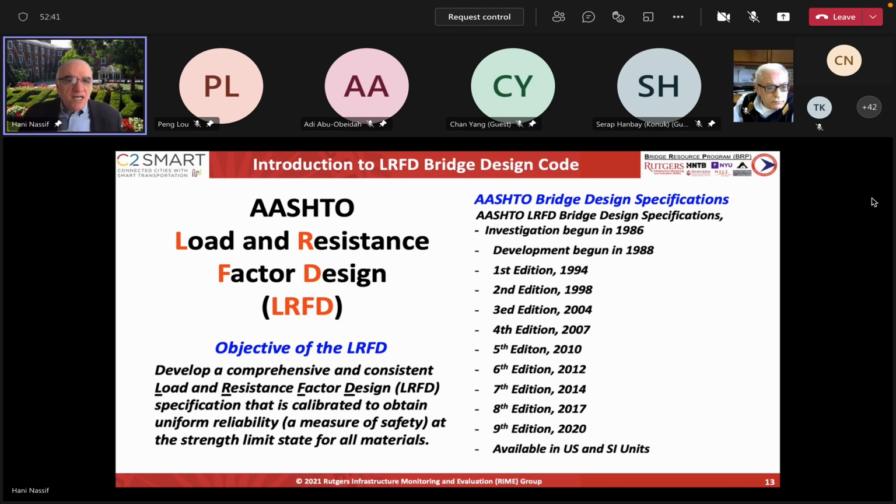Structural concrete varies from, and he referred to it as the partial pre-stressing ratio, which is a value of 0 means it's reinforced concrete, and a value of 1 means it's a pre-stressed concrete. And the specs are still unified in the AASHTO code.